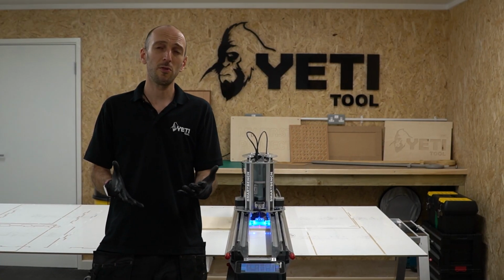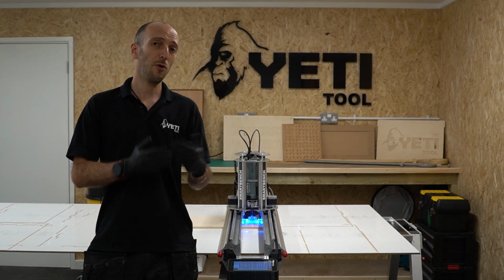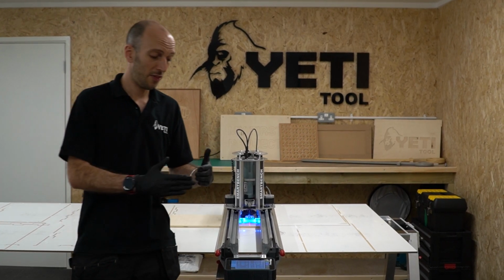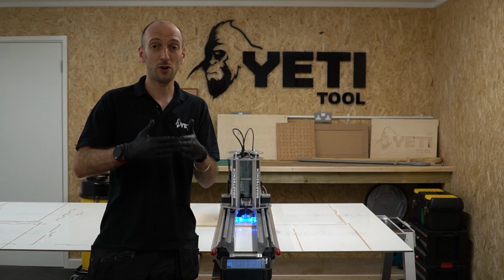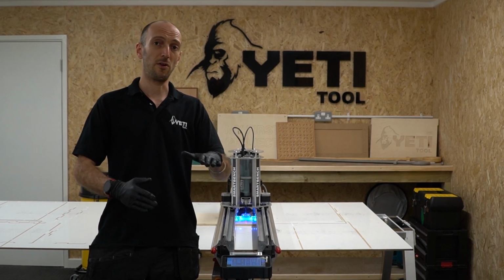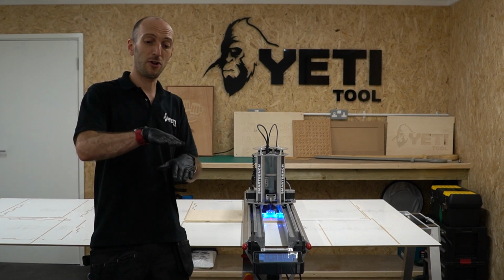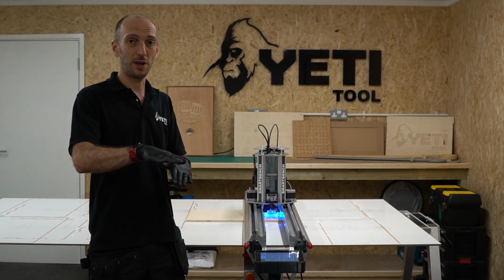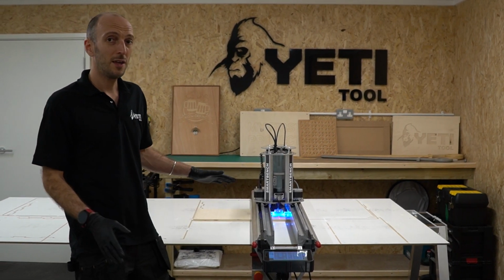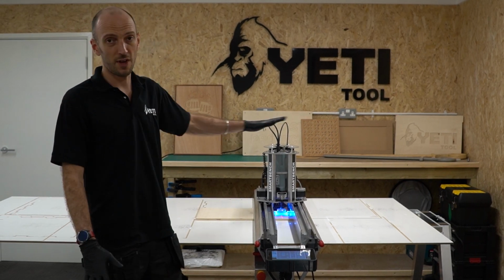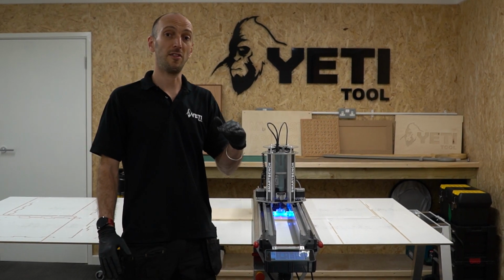A couple of notes when using the Pro plate. You'll notice that I didn't do it at the XY coordinates where there's only a corner to put the Pro plate on. I moved the Z head over, and that's so that I could get a solid contact patch with the Pro plate. And that's okay because the whole top surface of that stock represents the height at which the job datum is at.